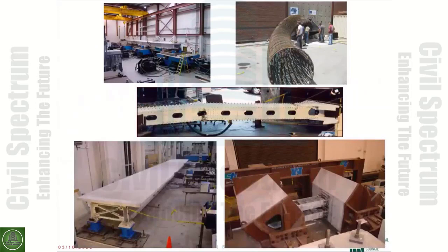These are a series of some of the experiments that we have done. The first one on the right is extremely important. This is a rebar cage that we failed on purpose to see the behavior of rebar cages during construction. As you know, we are not allowed to have any splices in the columns at the ends of the column, where we expect to have a plastic hinge.